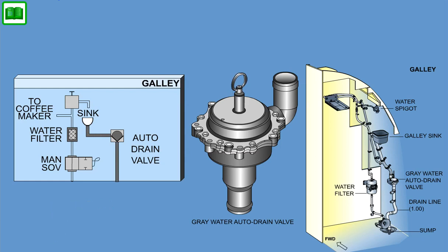When no differential pressure is applied, such as on the ground, the valve drains and no residual water remains in the valve. It is acceptable that the valve remains open on ground. In flight, the valve remains in a closed position until there is a head of wastewater at the inlet. The valve then opens automatically in order to drain the wastewater.